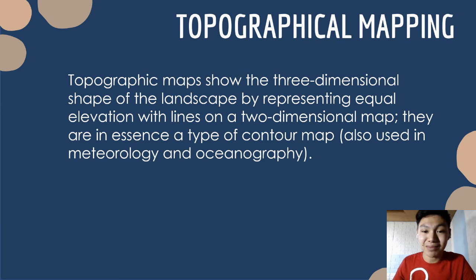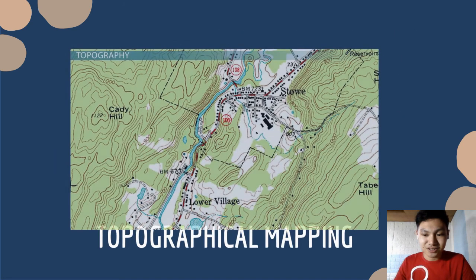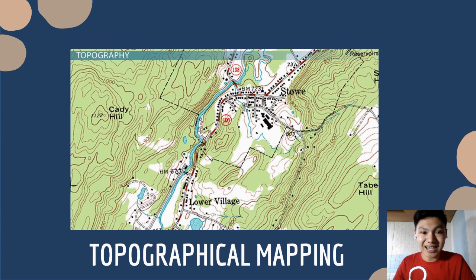Although this can be mathematically derived, most geologists create them by measuring the elevation, which is the position, in the field, or from an aerial photo, plotting elevation on a map, and connecting lines of equal elevation. It is much like connecting the dots except that all the same numbers are connected, rather than in sequence. Later, I'll show you some samples of different graphs and maps used in hydrogeology. Right, here is a sample of a topographic map.